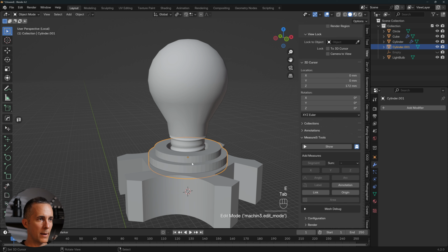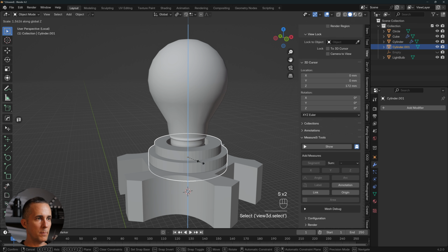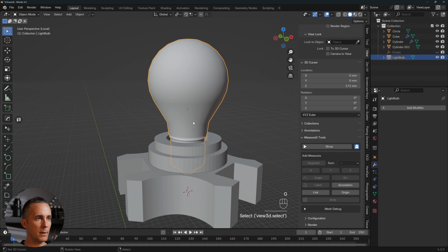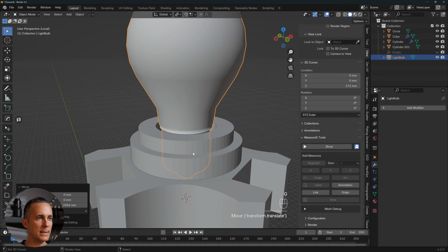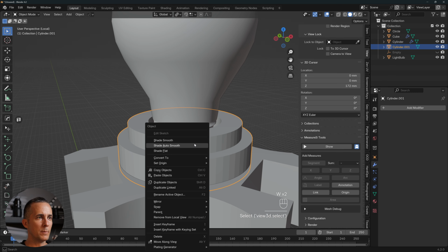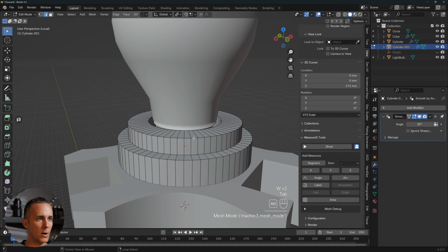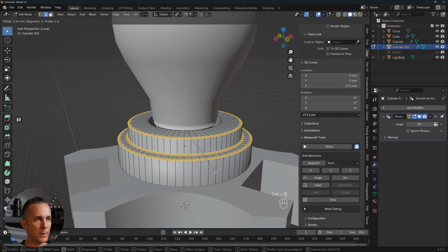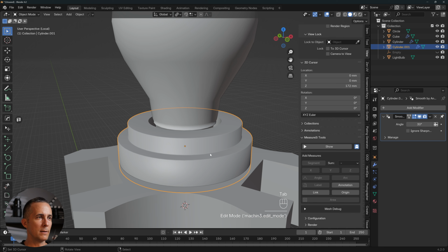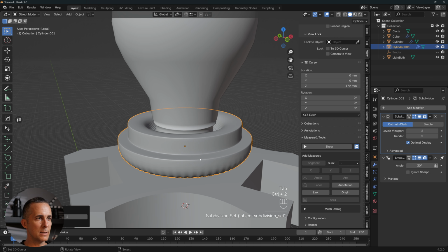down. And I want to move, oops, to make it a little bit bigger and move it up and move this a little bit down, and this is it. We can play a little bit with the edges here, so Alt and select this, Alt and Shift, select these edges and bevel it a little bit, maybe like that, and we can press Ctrl 2 to shade it smooth.